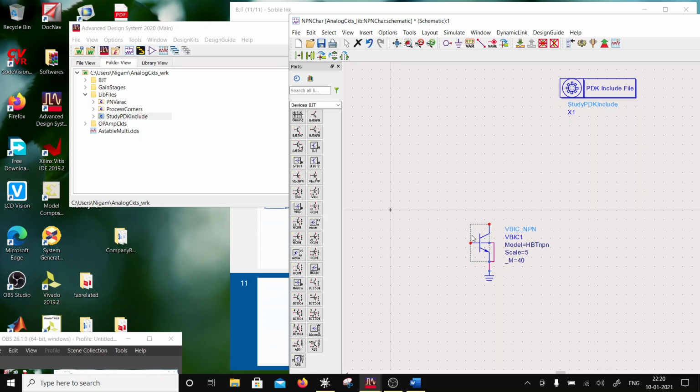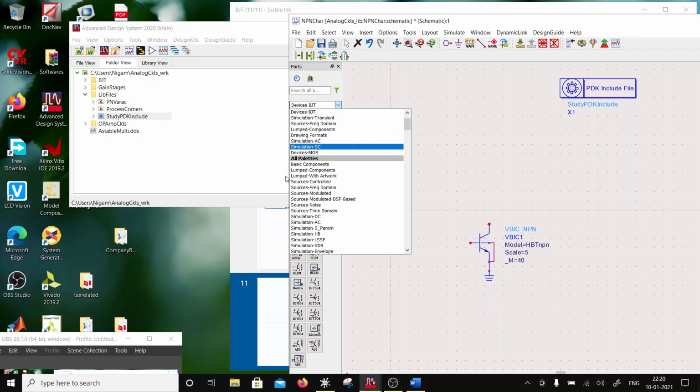And when you do analog design, you tend to just directly put the DC source here, and as soon as you put the DC source, it means that you are creating an RF short. An RF short means that's a reflection point, so that's not going to be a stable area, right?